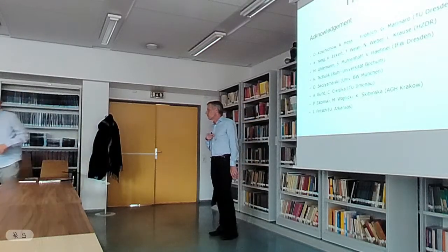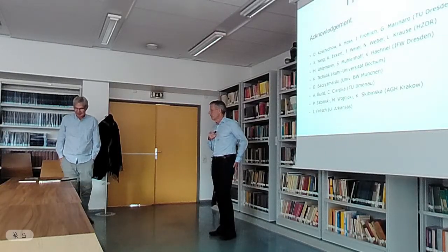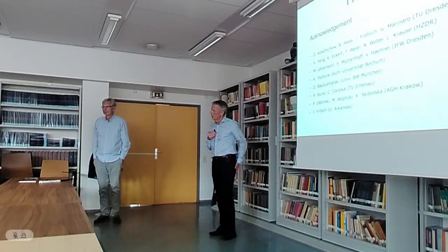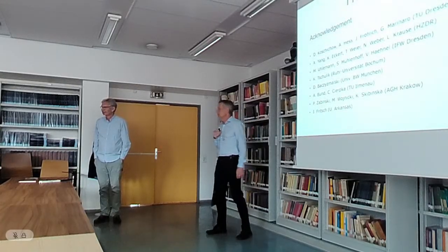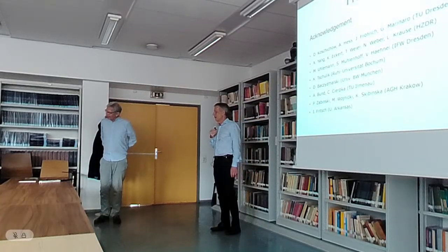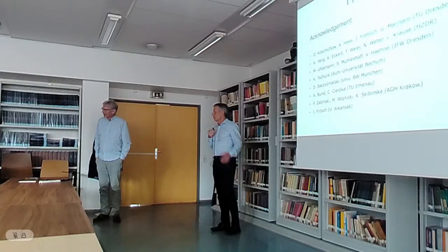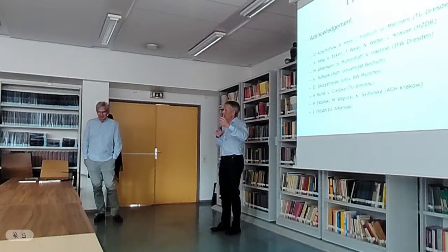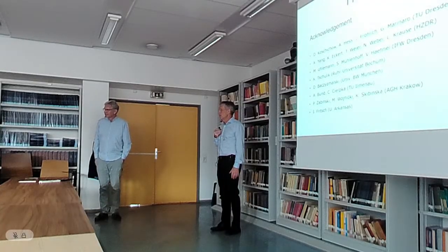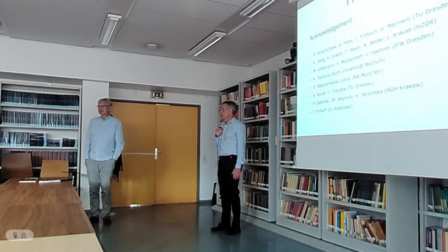Wei? Thank you, Professor. It's a very good presentation. I may have one question about the motivation of doing the magnetic field in water electrolysis. So you said that you can split the hydrogen and the oxygen by applying the magnetic field? No, that's just the motivation for the research of water electrolysis, not the magnetic field. The motivation for applying these magnetic forces is to shear and advect the bubbles out of the electrolyzer quickly in order to reduce the losses. Okay. So it's not possible with the Lorentz force to split the two different kinds of gas bubbles? No, it's a volumetric force acting on the conductive electrolyte. Okay.